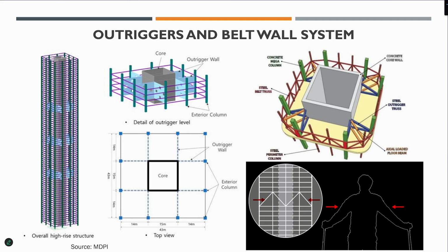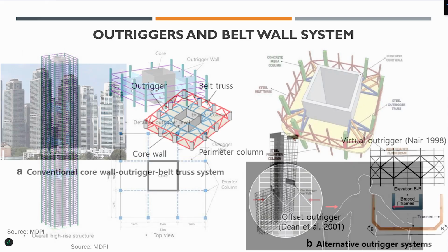So this is a good example of where outrigger walls are there with openings on every floor, but staggered, not at the same location, because that will weaken the whole thing. So you stagger them, that one floor is here, another floor is there. And then you can put those trusses, so you can see here, and then you can put these things here and there and there. So this is the concept of the outrigger.